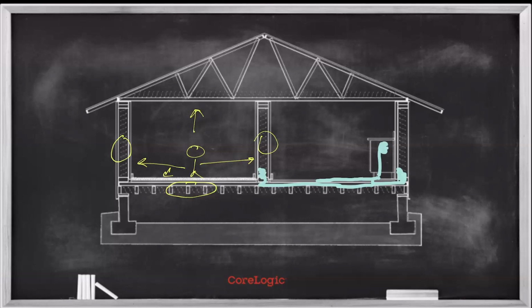And we could go through a pretty lengthy discussion on understanding that and then applying the art of tracking water migration, right? In simple terms, you have to measure for moisture everywhere that you reasonably expect moisture could exist as you track migration. If I know that the floor is wet at the foot of cabinets in a kitchen, for example, it's reasonable to expect that the floor beneath the cabinets is wet, right?